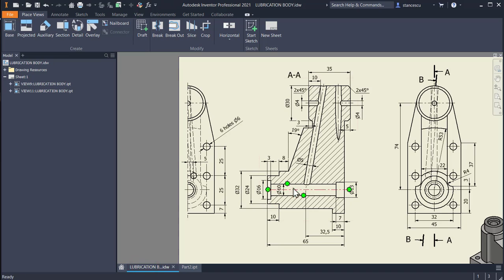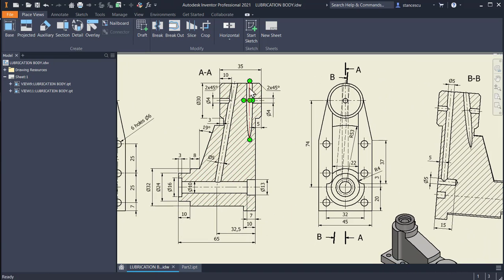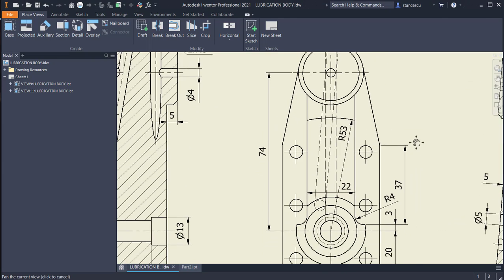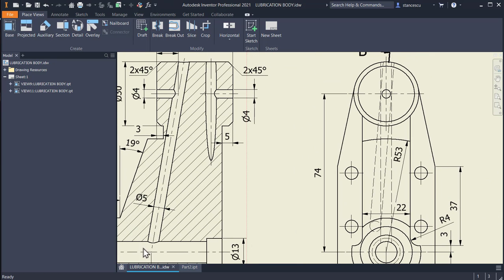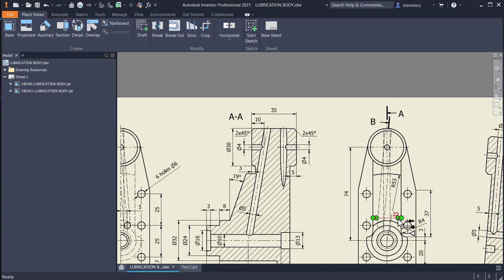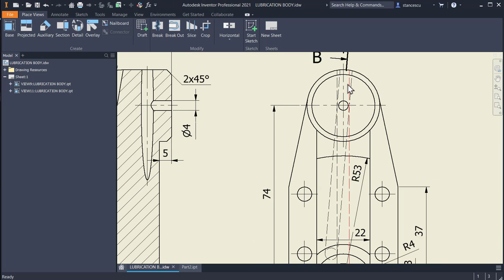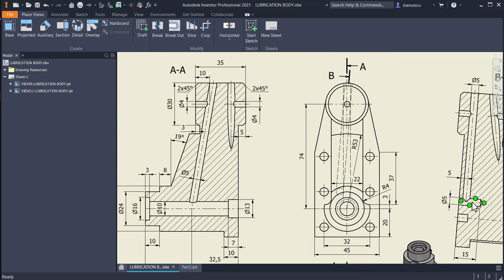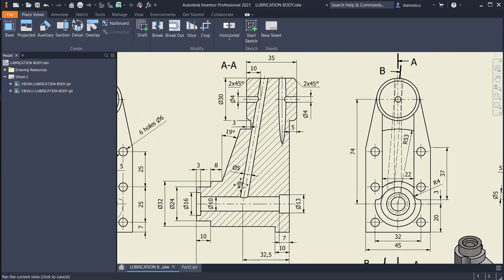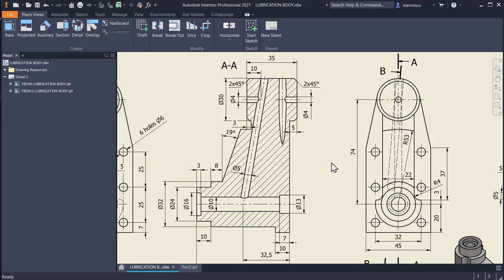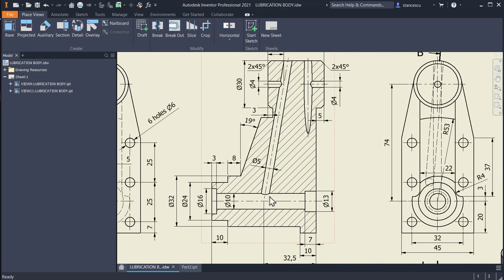Now we have to take care with these holes. 1, 2. You can see them here. One is this one along the part but sloped, and the other is this one, which is sloped in another direction, starting from this hole, which is this one. Let's start with this one by creating an axis, this axis, and a point of start here, not outside, because of the sloping entry. Yes, as you will see just now.